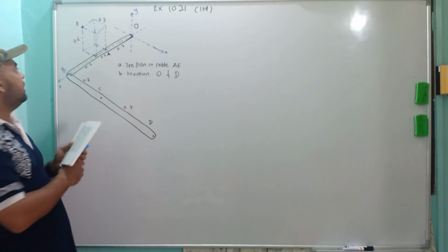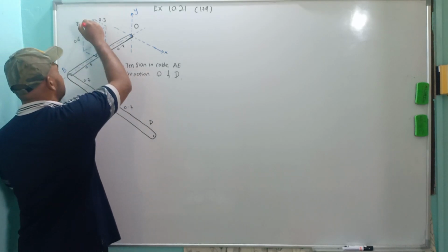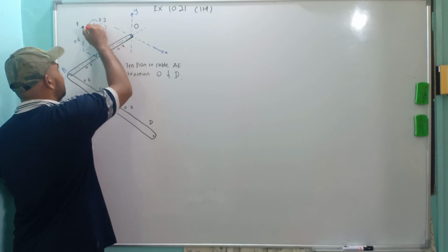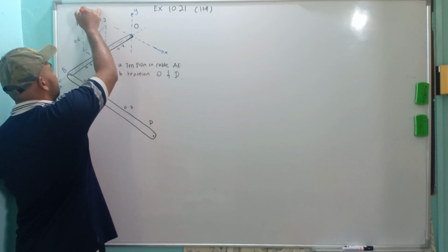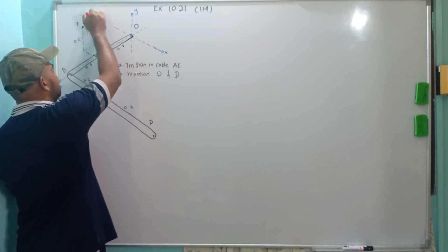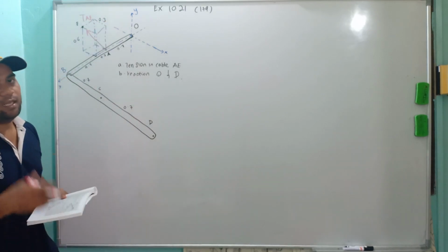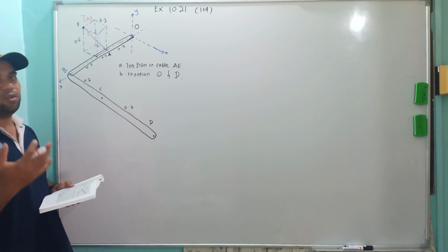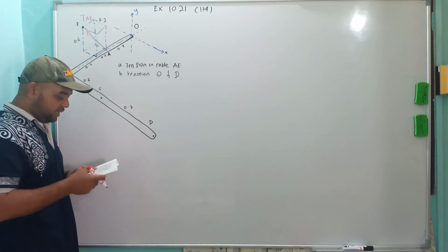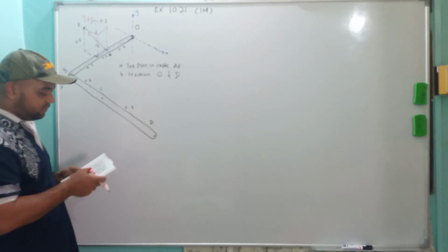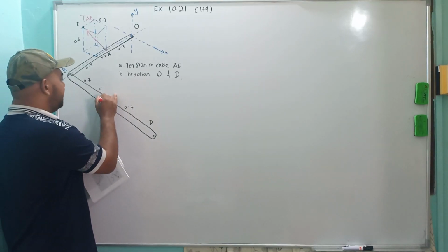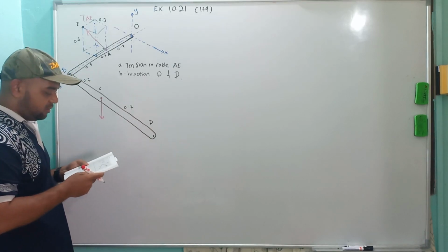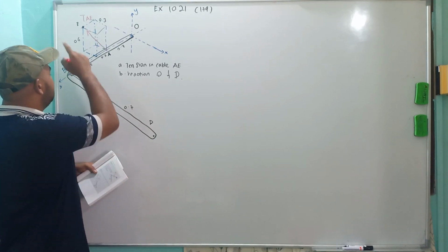The first one, from AE, we call TAE. The cable must always pull upward on the component; we always consider the cable to be in tension. Then we have a 75 kilogram mass supported by a cable, also going straight downward.